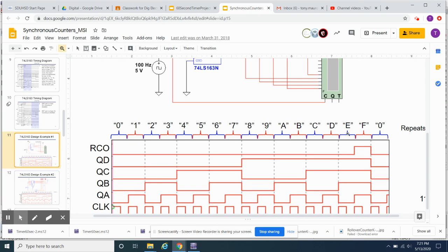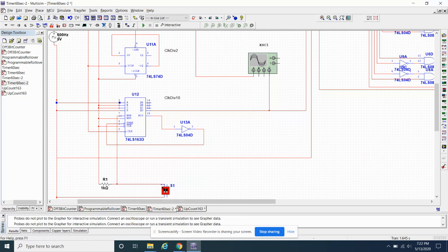One out of 10 clocks, it's going to come up. So that will effectively do our divide by 10, right? Because I'm taking this clock here and I'm generating this signal every 10 clocks. Well, that's a divider, right? That's just going to divide this, and I generate the signal every 10 clocks. Okay, so let's take a look at a circuit that would do that.